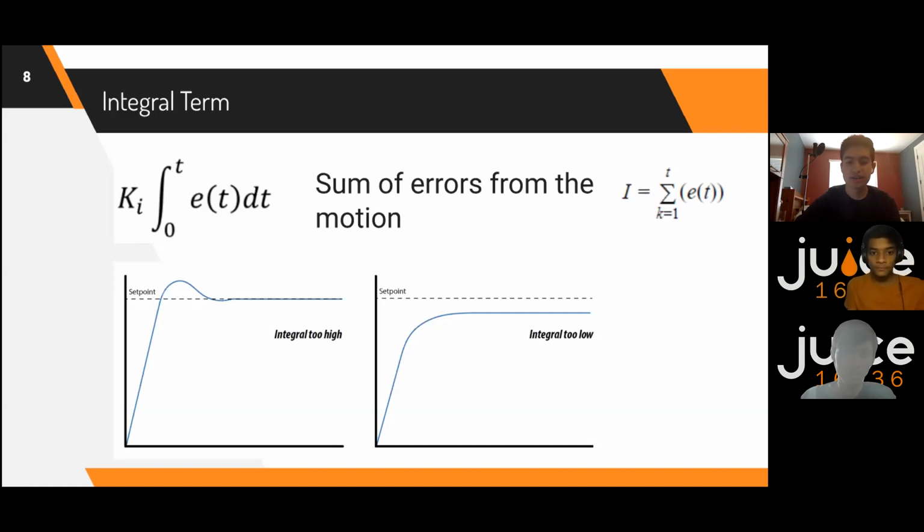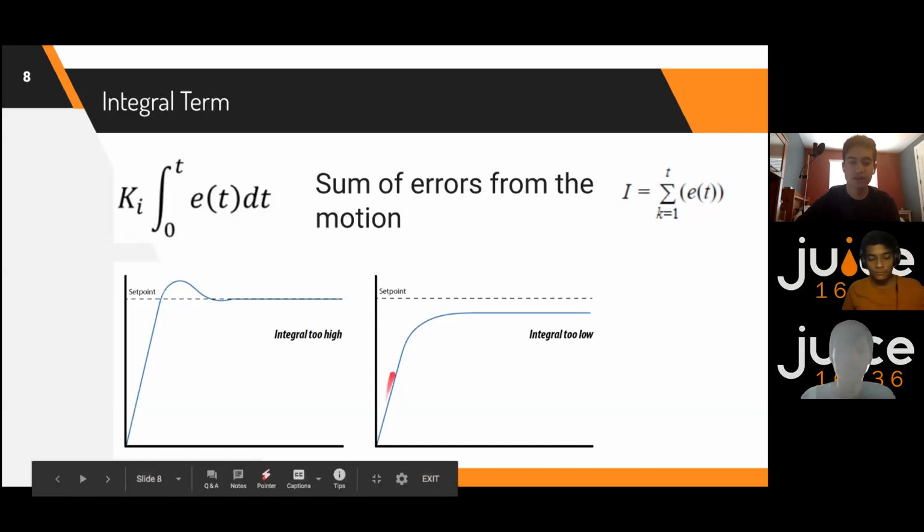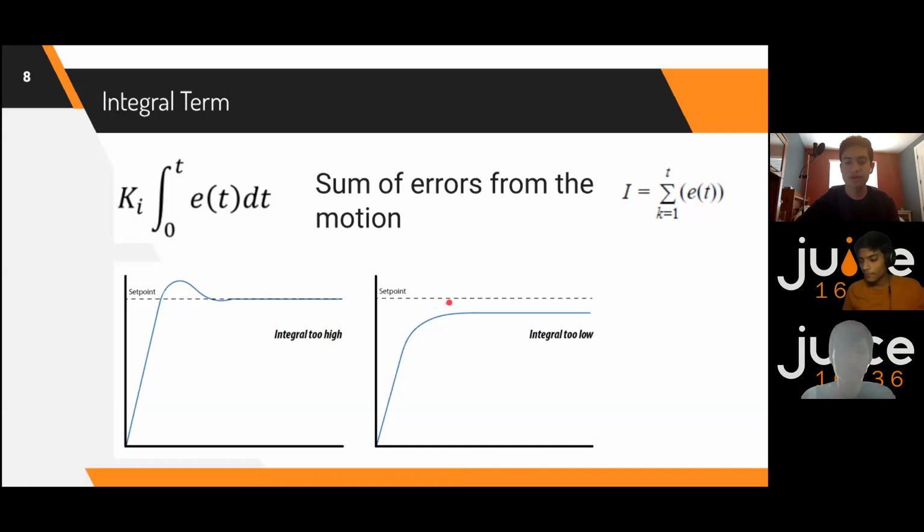So yeah, that's how you should tune the integral portion. Another thing that I want to mention is something called integral windup, which is basically if you actually reach your target with a proper integral tune, the integral portion of the PID correction will be built up quite a bit, so you'll just overshoot the target once you actually reach it. We'll address how to solve this issue later once we actually get into the programming of it.